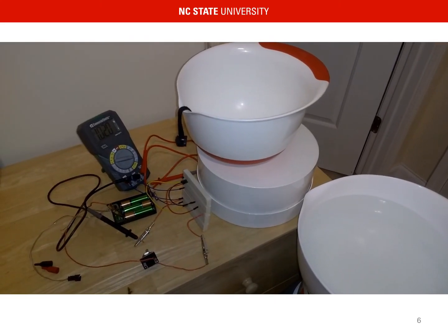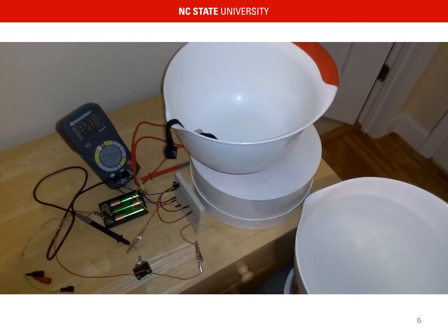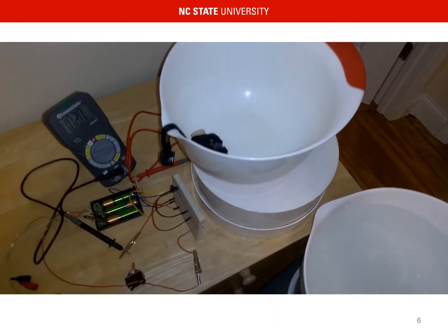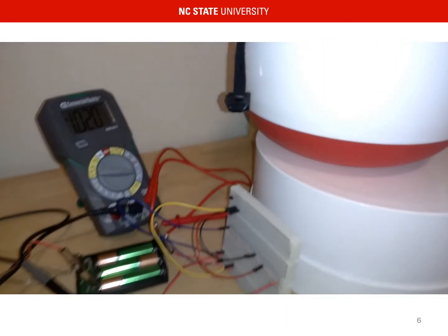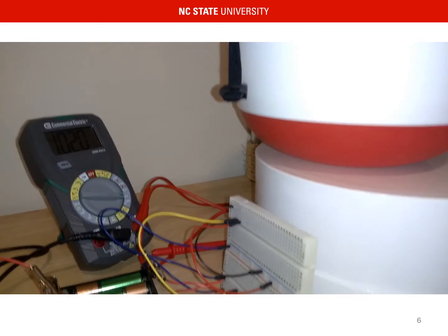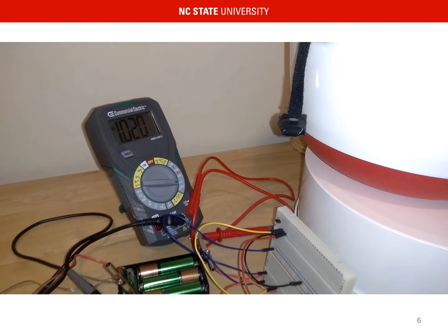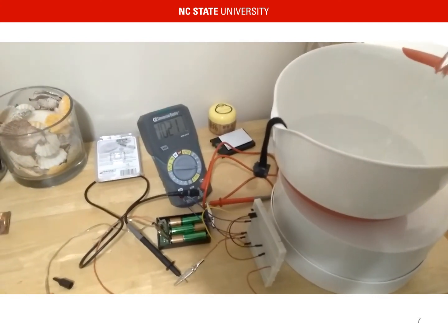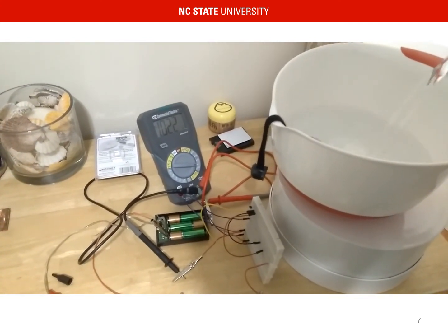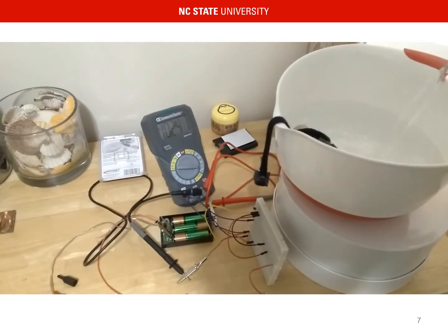Here I demonstrate how a Hall effect sensor can be used to determine the fluid level in a storage tank. We have a magnet suspended from a float which is located in our tank. Directly below the magnet we have our Hall effect sensor on the edge of the breadboard. The multimeter is set up to read the output voltage from the sensor. This tank is currently empty and the magnet is hanging at its highest position far from the sensor. We see a reading of 1.02 volts.